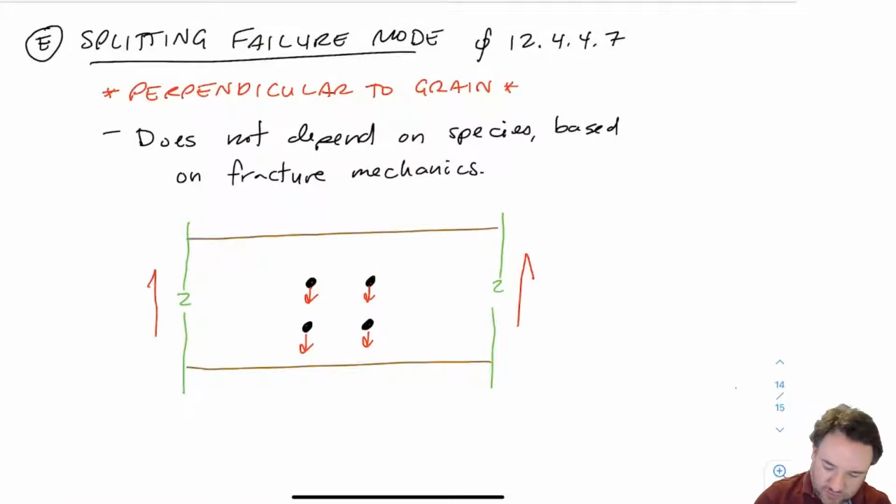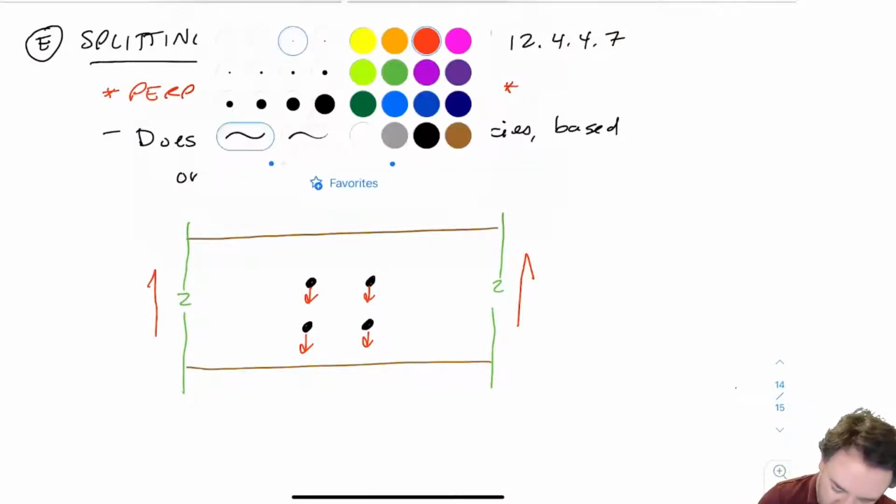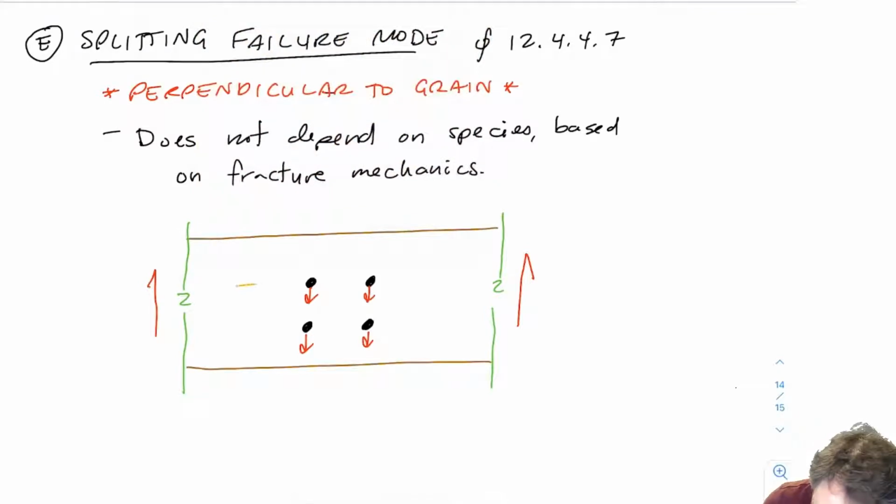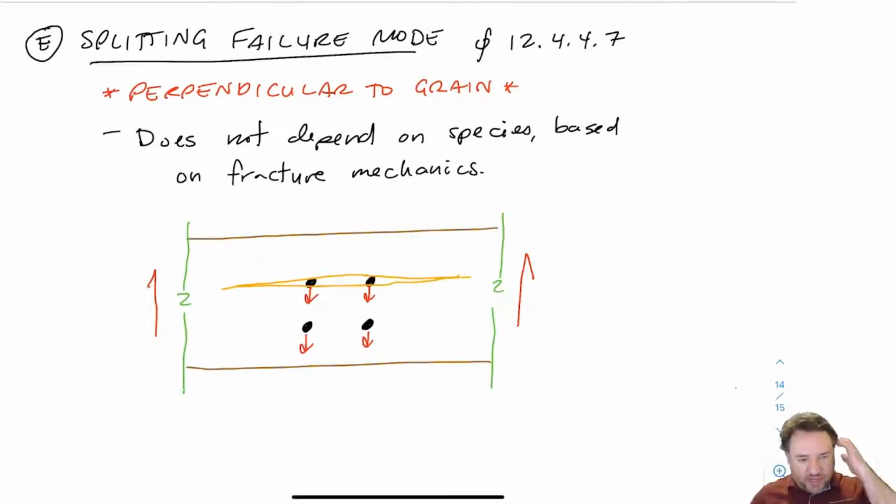So if we pull down those bolts, what's going to happen? We're basically going to form a crack here because we're splitting apart the fibers. That crack is going to have some certain length. And then if we pull enough, it's basically going to split the piece of wood crossways, which is very bad. So when we do this, we need to look at our unloaded edge and our loaded edge, and we're going to use these distances to calculate our splitting strength.